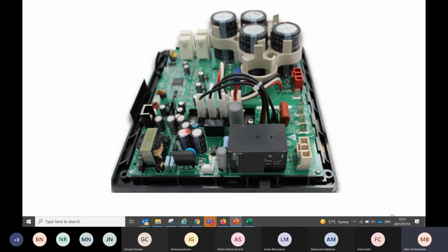It will then send a signal to this relay, and this relay is dealing with a lot more power. Here it's dealing with 2 phases. It's got a much bigger shunt resistor. That phase is already hardwired to the caps. It's going to bring in this phase and this phase through this relay shunt resistor, and these caps are going to be ready for work, sitting there at 560 volts. So that's pretty much how these boards charge up.